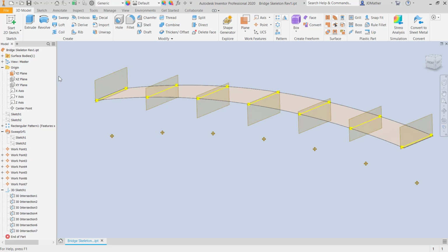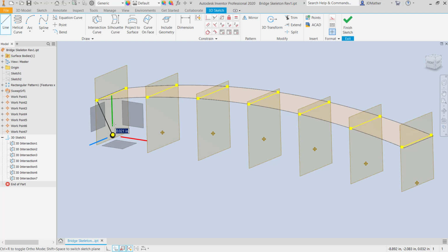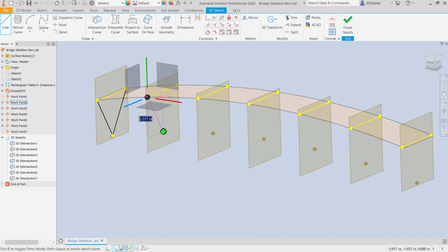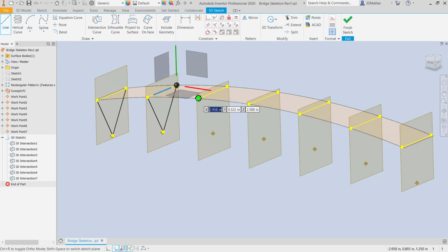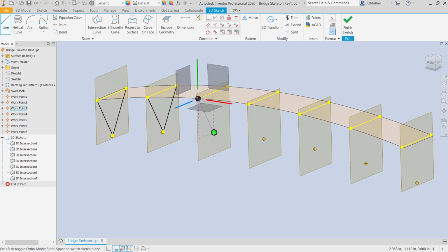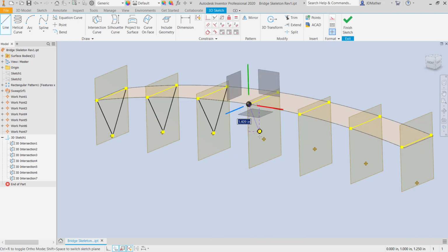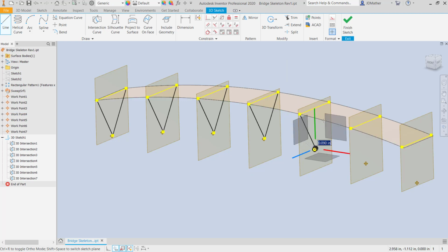I will drag the end of part marker below the 3D sketch, and then I'm going to edit that 3D sketch, and I'm going to draw a line from this point down to this point and back up to that point. I'll right click, say OK, then spacebar to get the command back from this point to this point, right click, OK, spacebar to get command back. So we'll see how we're going to put all of these triangles in here. Got 3 more to go.